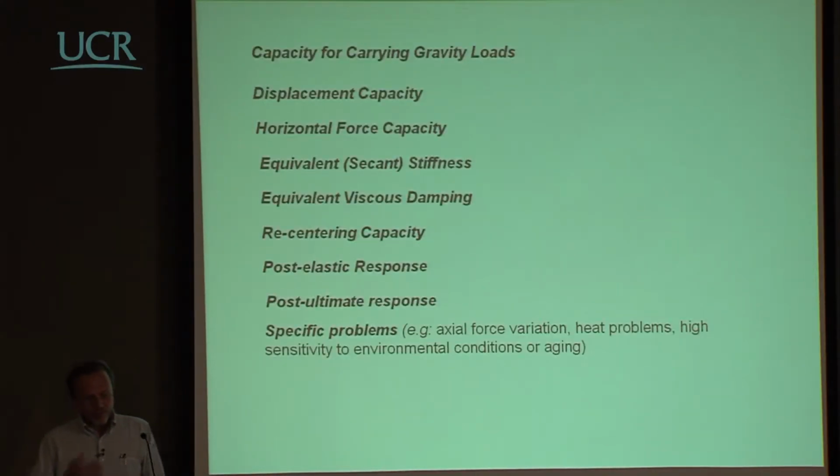So I will try to go very briefly through all the points that we need to touch. Of course, the capacity of carrying vertical loads, gravity loads, at least for certain classes of isolation devices. The displacement capacity, the horizontal force capacity, the equivalent secant stiffness, the equivalent viscous damping, the recentering capacity, the post-elastic response, and the post-ultimate response.